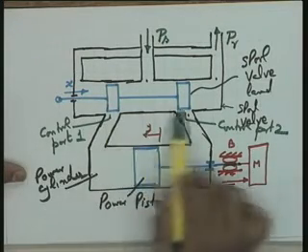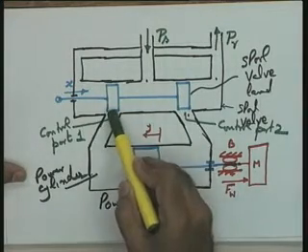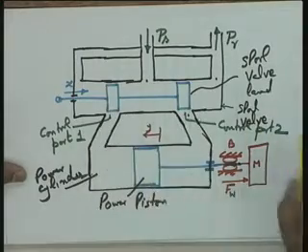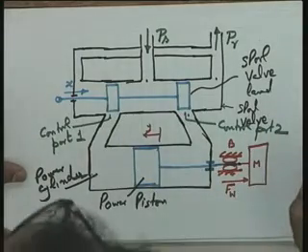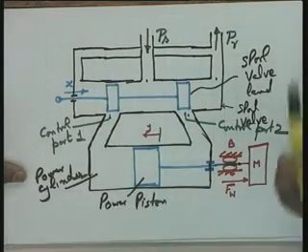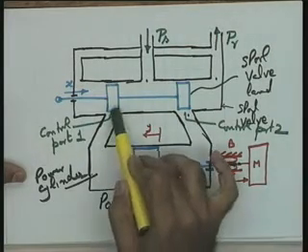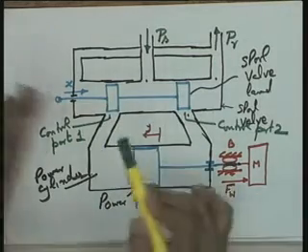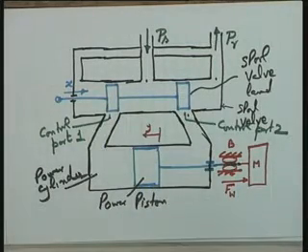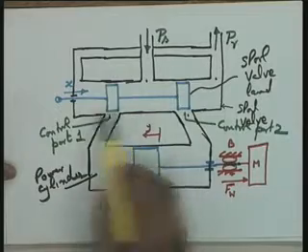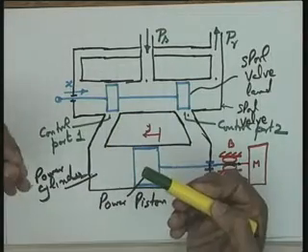Now look at the control ports once again. I said that this completely covers the load, the particular port. Unfortunately, it is not possible. There will always be some manufacturing tolerance. It's absolutely not possible that this will completely cover it. So you see the construction, two-way construction is possible: either it may over-cover it or it may cover it slightly less. I will take this slide and bring it back again. In this particular case, two types of constructions are possible.